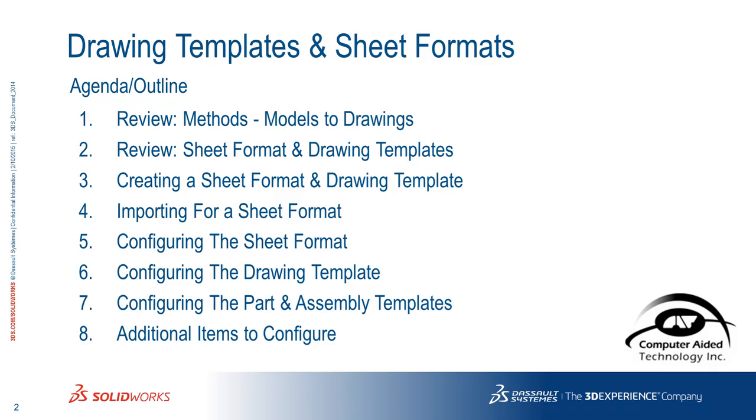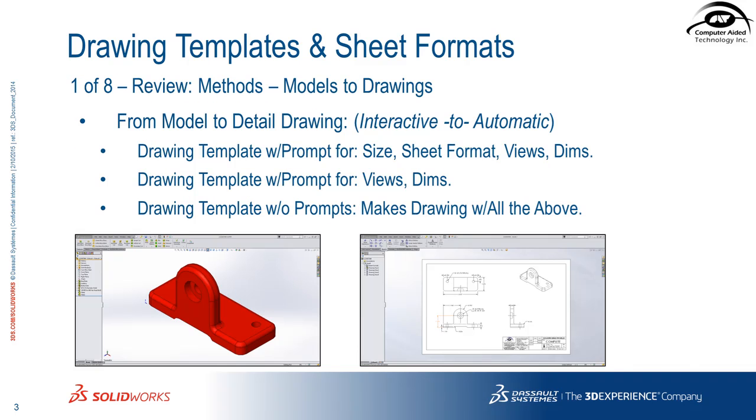The drawings course through your reseller or whatever has this kind of information that I'm going to present. It's one particular lesson of that course. And I feel that they teach it backwards, because when I teach it, it starts with changing things and setting things up and making it look good and work. And the last thing you do in the lesson is import the DWG file. And for every customer that I've helped get their drawing templates moved over from something else into SOLIDWORKS, I started with the DWG file. So that's how I'm going to present it, in a more chronological order.